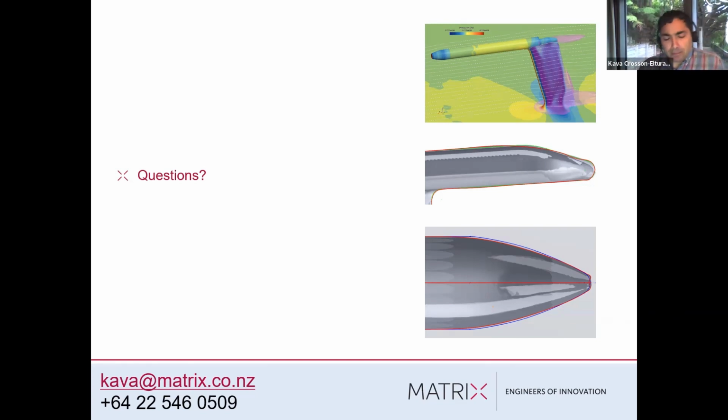I haven't done any validation on these solutions yet, so I can't speak to that so confidently, but my intuition is that if you've got the flow field roughly correct, then the adjoint solver is going to find a solution that's fairly robust for a variety of different mesh conditions, which are obviously just a modeling artifact, but also flow conditions. So just from what I've seen so far, it tends to produce fairly robust solutions. I haven't done any real validation of those solutions yet, and I don't have the facilities to do that, but I would definitely be interested in cooperation if anyone does.